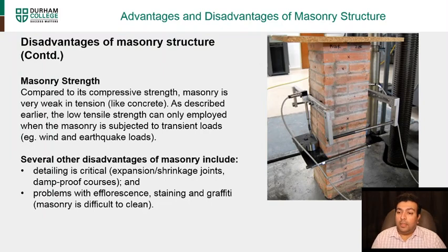There are several other disadvantages of masonry, which include detailing, which is critical. Like we said, you need good skilled people so they can include the expansion and control joints and damp proofing courses. Those are very important. It also has problems with efflorescence, staining, and graffiti. Masonry is very difficult to clean because of the textured material. You cannot wash it down as easily compared to concrete. Those are some of the disadvantages of masonry structure.